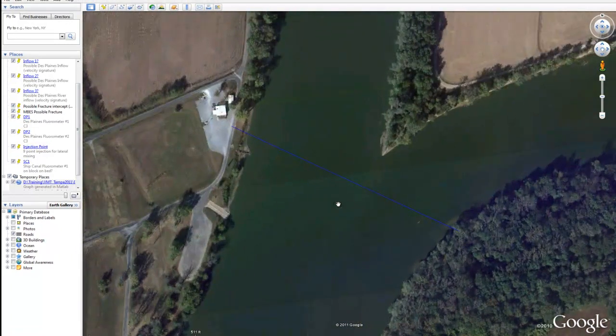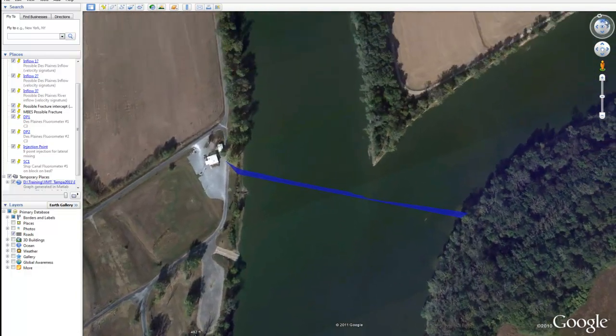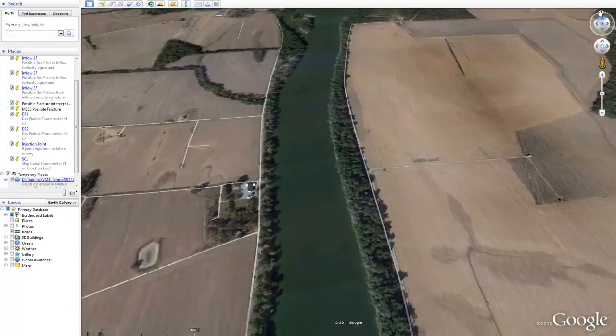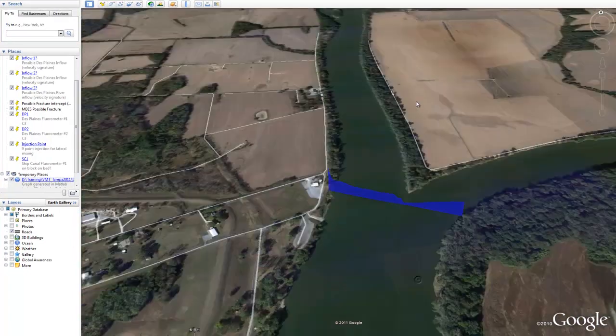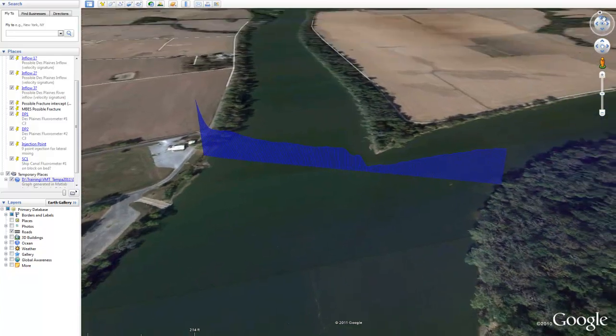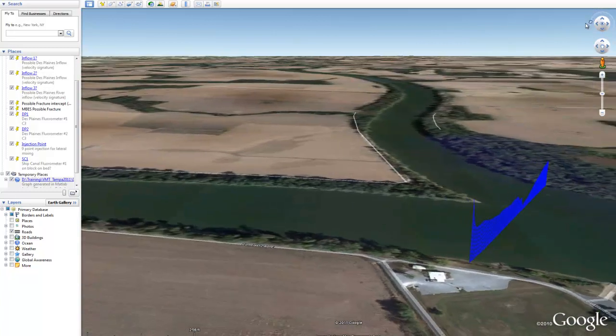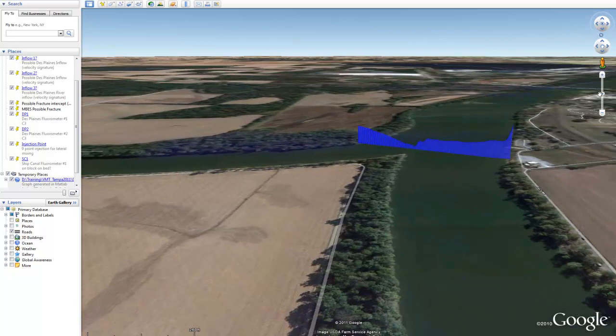And right now, we're looking straight down on our cross-section, so it doesn't look like much, but we can navigate here and pan the camera, and zoom back, and we see that now we're looking at our cross-section in 3 dimensions, looking upstream here. This is the Wabash River and the White River coming in, and we see the nice scour zone that's concurrent with the shear layer. You can rotate this in 3 dimensions here, rotate and get a downstream look.